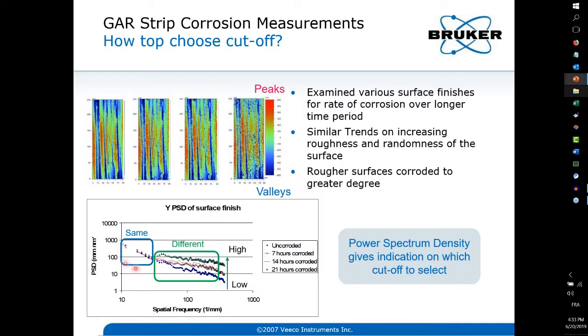And what we see here in terms of that part is really more or less what we call waviness, and here will be more the roughness filtered. And what we see is the waviness here is fairly the same whatever the corrosion state, but after that you see after a certain spatial wavelength, around 30 cycles per millimeter, we start to see differences.